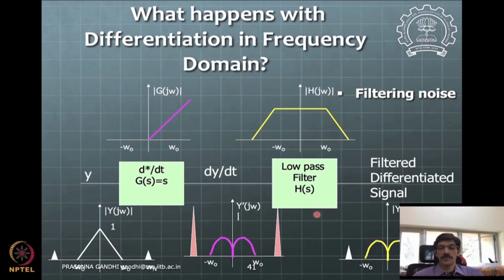So sources of noise are not only whatever ambient sources, but your mathematical operations can also enhance the noise that is already there in the signal. Okay. So we have not yet talked about this: this is ideal differentiation, but if you have a forward difference or backward difference, there is a different form that will happen here, which we are not bothered about for now.